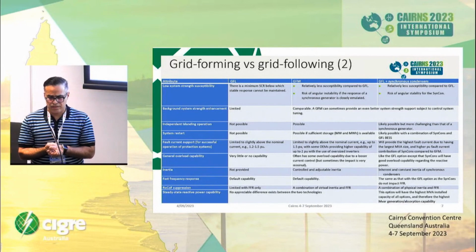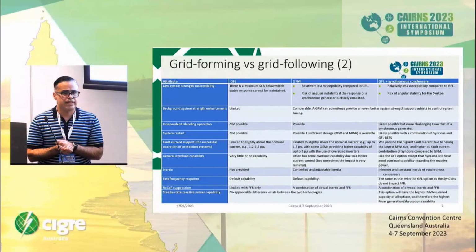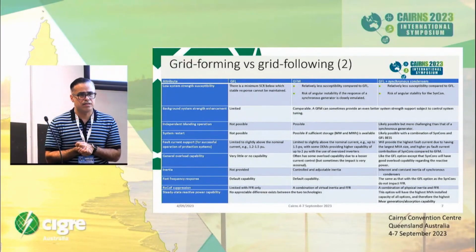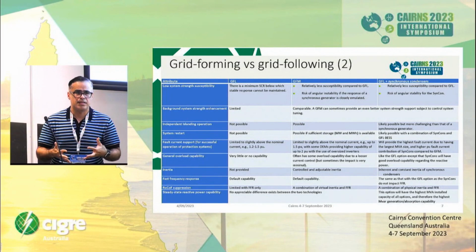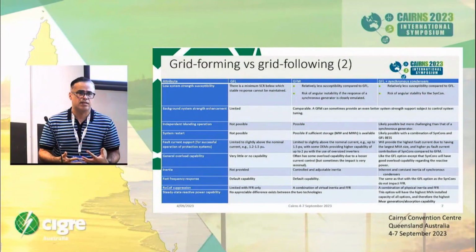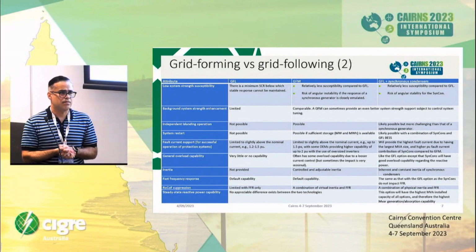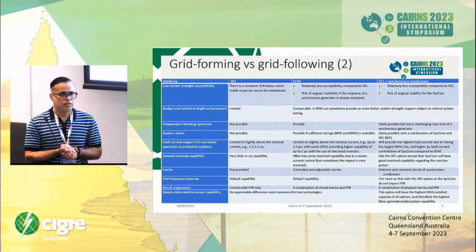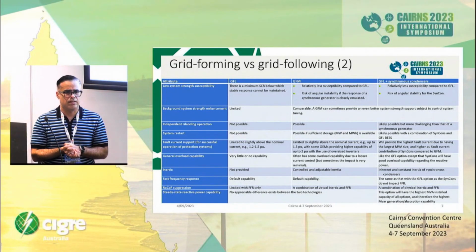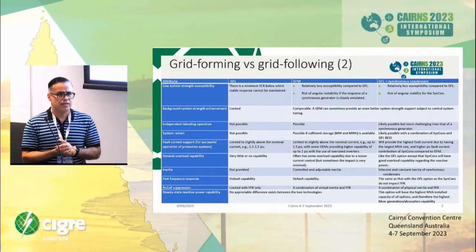And the first two perhaps are some of the most important ones in terms of determining what we need for system restoration, which is the ability to withstand certain system strength. As we are restarting the system, even with a synchronous generator as the black starter, the fault level available in the system is going to be very small, and how you can bring in IBRs. Obviously, if you use a grid forming or combination of other IBRs to restart the system, that would be different.